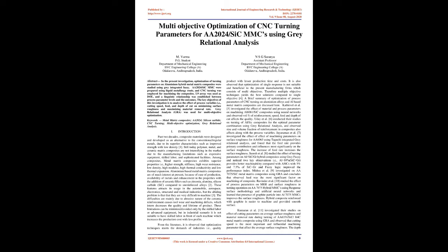The difficulties are mainly due to the abrasive nature of the ceramic reinforcement, which causes tool wear and machining defects, which in turn decrease the quality and lifetime of the product. These limitations can be minimized or avoided only by skilled labor or advanced equipment, but in an industrial scenario it is not suitable to have skilled labor in front of each machine, which increases the production cost with less profit.